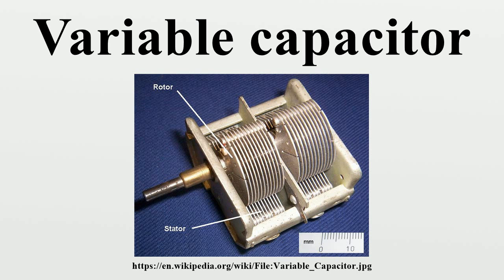When the shaft is turned, the plunger moves in or out of the sleeve and the value of the capacitor changes. The vacuum not only increases the working voltage and current handling capacity of the capacitor, it also greatly reduces the chance of arcing across the plates. The most common usage for vacuum variables are in high-powered transmitters such as those used for broadcasting, military and amateur radio, as well as high-powered RF tuning networks. Vacuum variables can also be more convenient since the elements are under a vacuum. The working voltage can be higher than an air variable the same size, allowing the size of the vacuum capacitor to be reduced.